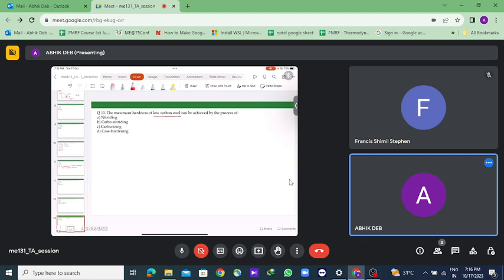Is it the carbon content or anything? Yes, it is the carbon content. See, martensite transformation will result in a higher hardness when a greater fraction of carbon is present, as I already said, due to the diffusionless transformation of BCC to BCT structure. So the more the carbon atoms, the more carbon atoms will be in a position where they should not be.